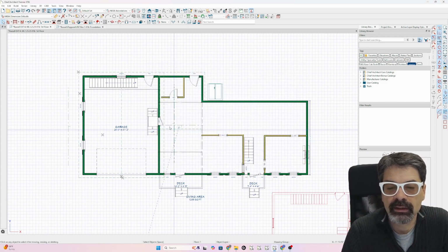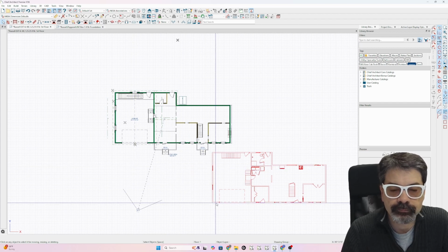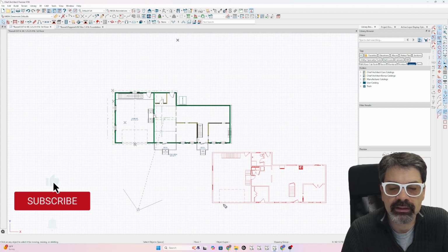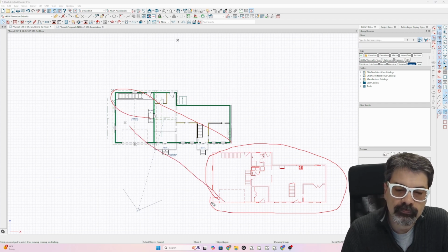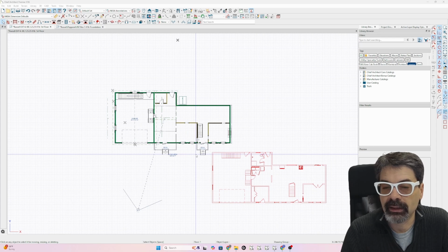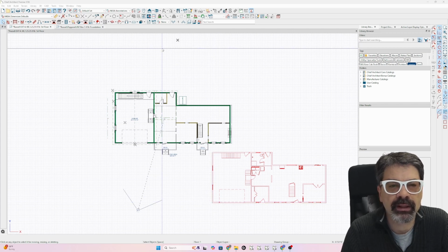I'm going to click OK, and I'm going to notice that in the two files, the plans were created on different XY coordinates. So to get this plan to overlay without moving everything, I could move everything over. Version X15 gives us the option to do an XYZ move to just shift, if you will. It's not actually moving, it's just shifting this reference display.